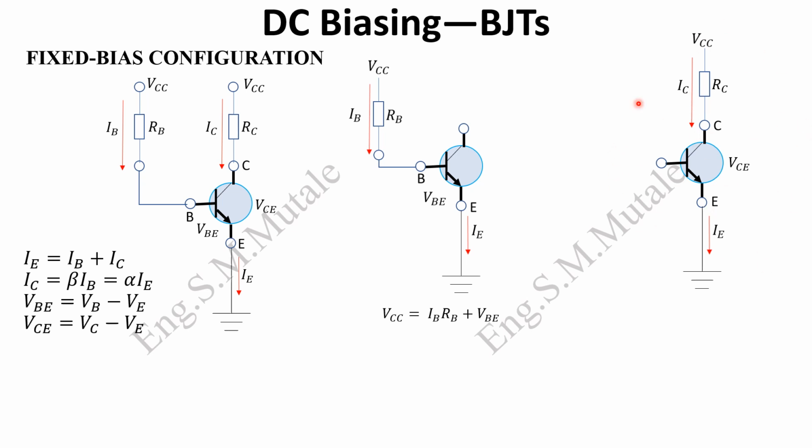From this, it's very easy to derive the equation. This voltage VCC is going to drop across that one, and then it will go to the ground. With that, you're going to derive this equation: VCC is basically the summation of the voltage drop across the resistor on the collector, which is IC RC, IC being that current and RC that resistor, plus VCE. So we've derived these two equations. Pick that route, you're going to have that. Pick that route, you're going to have that. And then you can solve for whatever they're asking for. On the next slide, we're going to look at an example.